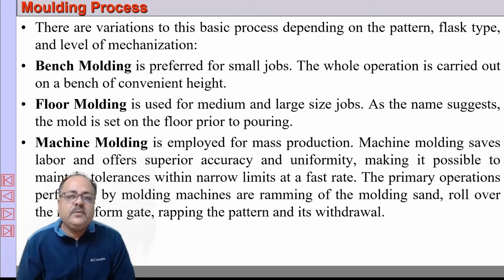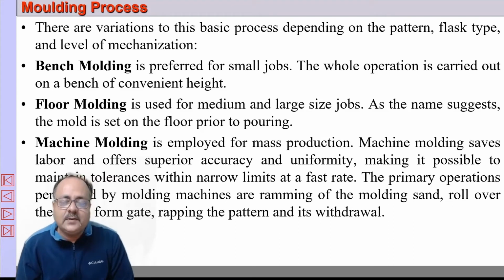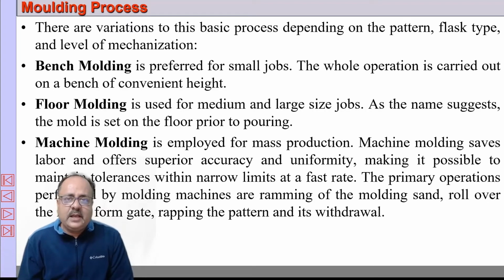Hello friends, welcome to this lecture 6 of a series of lectures on metal casting. In this lecture, we will be discussing molding processes. Molding processes can be carried out in various ways. It can be bench molding, where we carry out molding of small jobs and the whole operation is carried out on a bench of convenient height to the foundryman.